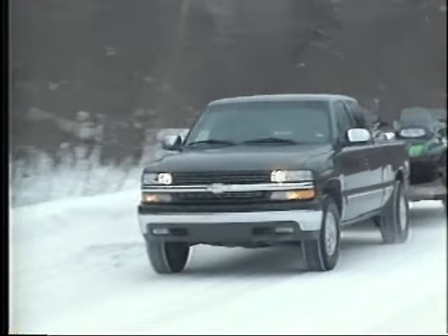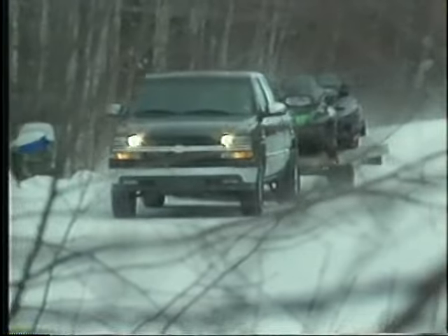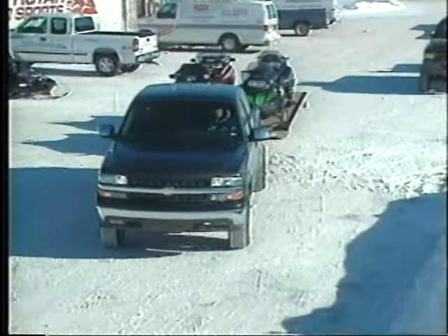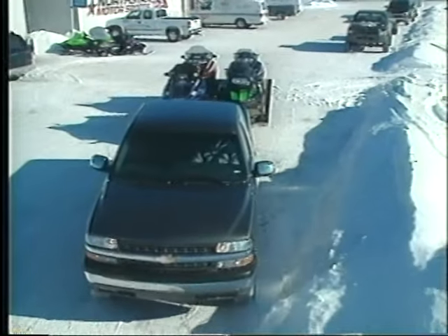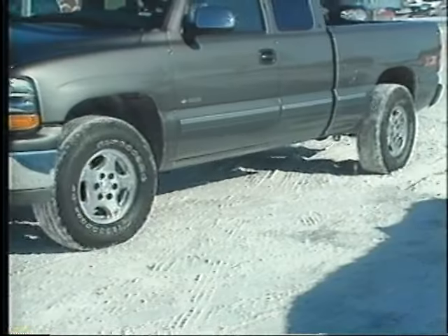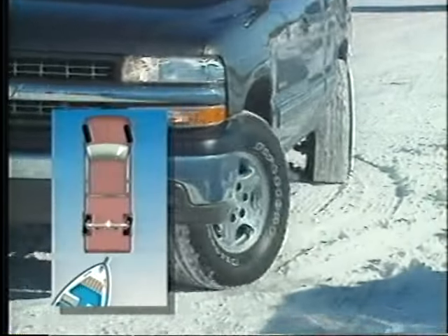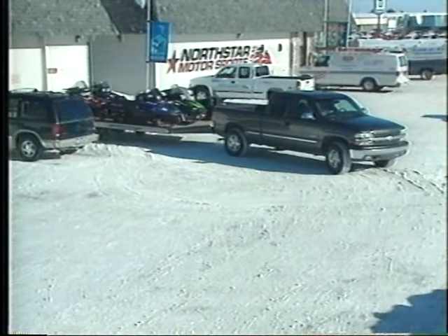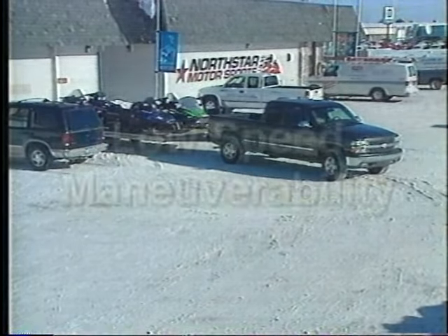The stability of rear wheel steering continues with the trailer attached. The system continues operating in positive phase. This allows the trailer to track the truck more directly. With rear wheel steering, backing and parking a trailer becomes easier, particularly when additional maneuvering space isn't available. When operating at slow speeds in the tow mode, the rear wheels turn the opposite direction of the front wheel. This allows for much easier maneuvering of the trailer, particularly in tight spots.